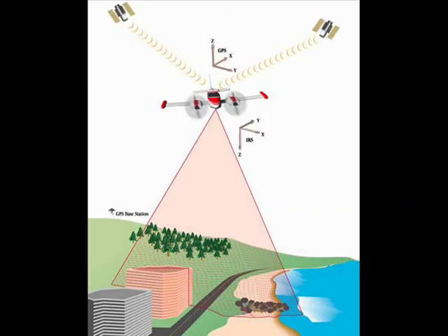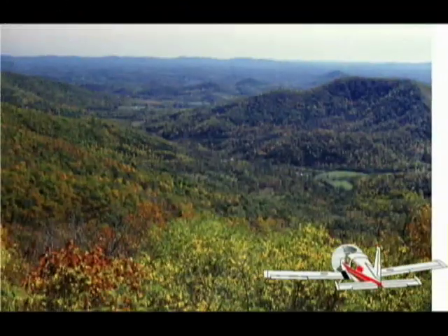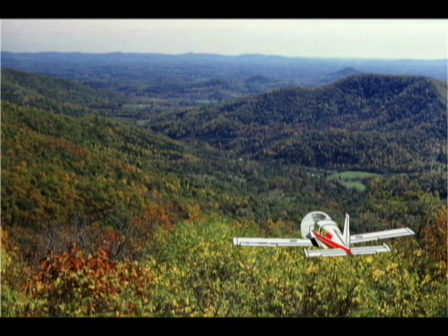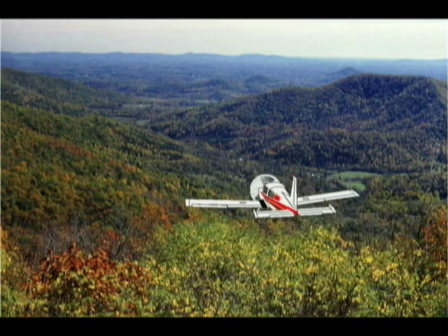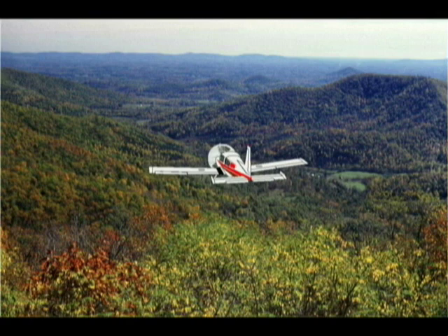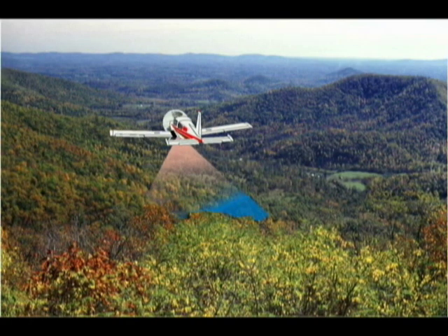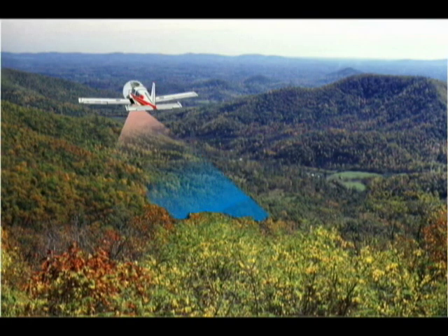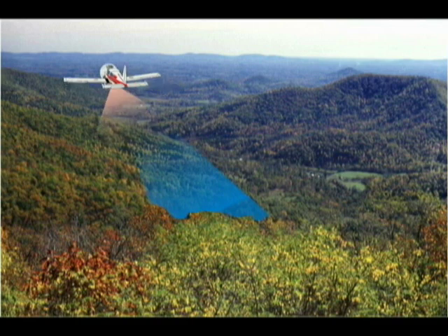This records all the data from all the systems and sensors and converts it into millions of XYZ coordinate points. All these components together, the laser, the IMU, the GPS, and the computer, are the basic units of the LiDAR system. From the LiDAR platform, the laser fires thousands of pulses to the ground every second. The scanning mirror detects these pulses in a swath following the flight path. These are reflected back to the onboard detector where distance to target is measured.